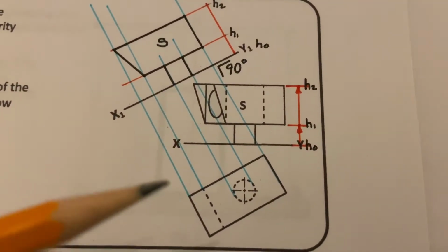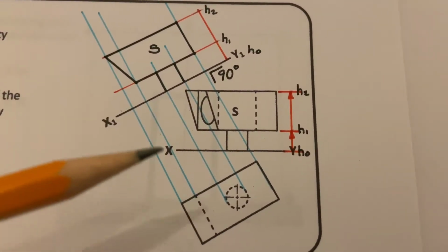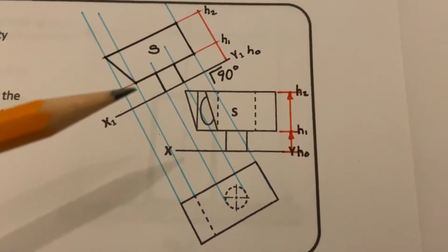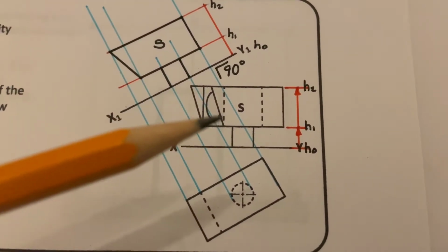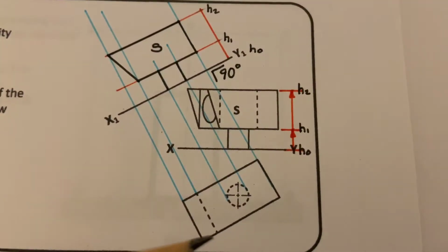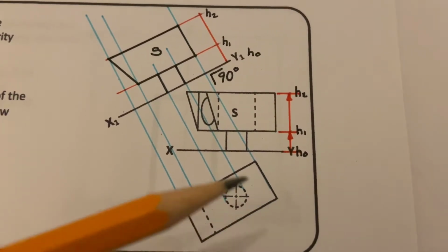So when you project up this here, you get that point there, and then we have the hidden detail line down here, so we connect them together with a diagonal line. Then this line runs along the bottom here to the very end of the camera. So the dotted line there, you'd have the line running on to the very end of the camera.